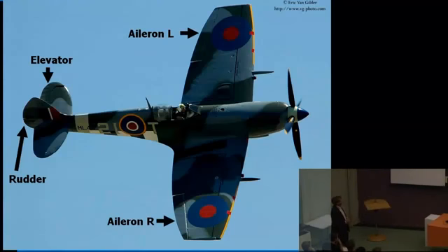Other control surfaces, the elevator, which takes care of the pitch control. This is the roll control, pitch control. And the yaw control is done by the rudder, though they do not work fully independent. If you move the aircraft laterally, you in general will want to control both with the aileron and the rudder to avoid the aircraft from slipping through the air. If you just push the rudder with the pedals, that feels very bad if you're in the aircraft. It's not very comfortable. In modern airliners, you often have the yaw damper in there, which will also control the rudder to avoid slipping maneuvers with the airliner. This is, by the way, a Spitfire which has clipped wings for low-level flying.